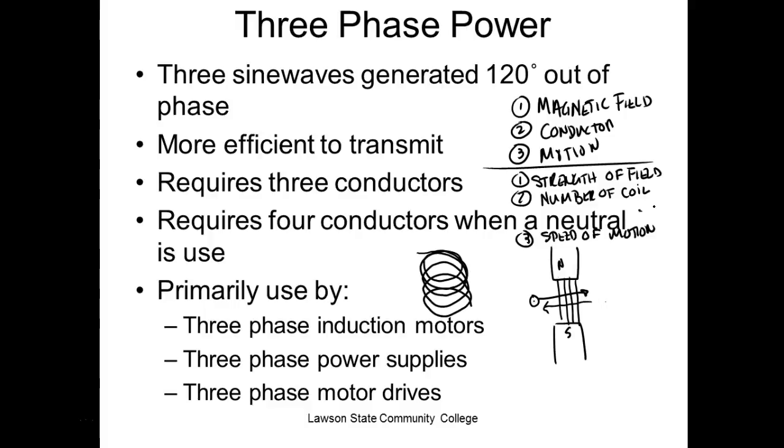And how much current, what determines the resistance of this would be the gauge of the wire. A lot of people say, well, all this does is give you the amount of voltage that's available. But you got to remember, if you push current through a wire, if a wire has a resistance, it's going to drop a voltage. So this is why your big high current generators have a lot of coils of wire, but it's a big gauge wire, right? You understand? Because what we're trying to do is reduce that resistance. But it's got to use a lot of wire because the only resistance it gets is the wire itself.